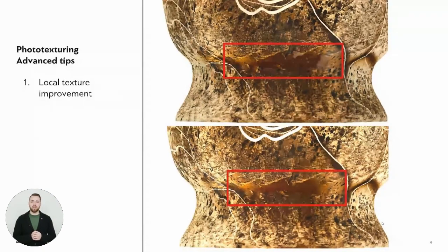I would like to point out that when we add new pictures and import them into Artec Studio, we recommend re-importing the entire photo set and running photo registration for it as a whole. So old pictures plus new pictures. Photo sets that have already been registered once in Artec Studio should not be re-registered because the algorithm slightly modifies them, and the result of the repetitive photo registration of one same photo set may be unpredictable.